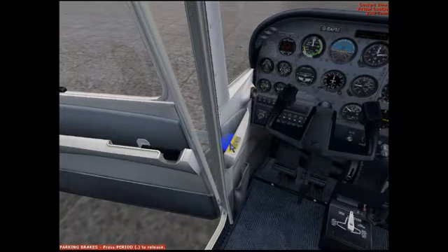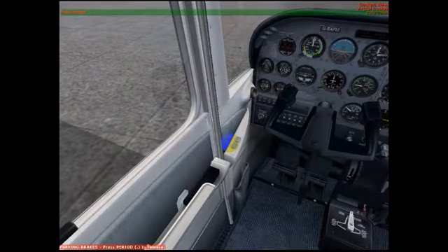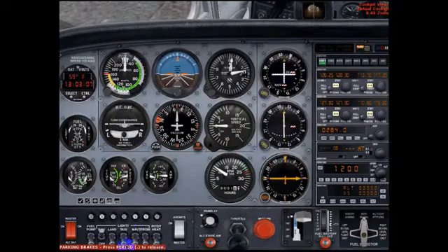All right. Let's close the door. All right. Exit closed. And shift forward. Now, some things we can see now. Before, when the engine is off, the fuel flow was actually down. All right. The EGTs come up. The oil temperature is going to start warming up, but it is in the green arc, and the pressure is below. If we just throw our throttle in, just fire it up a little bit,